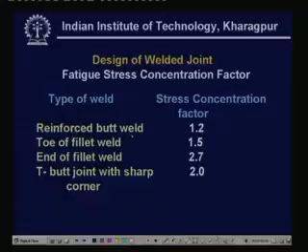So, if crack initiates, then it will propagate when the loading is alternating or variable. So, the stress concentrations will be important there. Remember, in the static loading, the stress concentration is not that important, because always there will be some plastic deformations which will take care of such enhanced loading, enhanced stress. But if the loading is fluctuating, the stress is fluctuating, then the crack can easily propagate. So, this is very dangerous. For different weldings, we have different stress concentration factor. So, we have what is the Kf here.